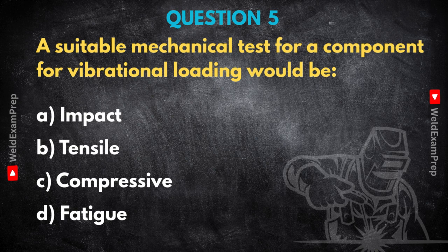Sort of, but it's a specific mechanism called fatigue. Fatigue is the weakening of material specifically because of these repeated cyclic loads. It causes tiny cracks to start, often at microscopic flaws, and then grow with each cycle until the component suddenly fails. So the test, designed specifically to simulate this kind of cyclic loading and measure a material's resistance to it, is fatigue testing. Fatigue testing makes sense. How does that differ from the others then?